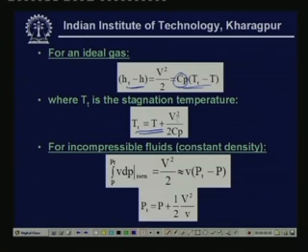Okay. And you have to be careful about the units here. When you are using Cp as kilojoule per kg Kelvin, and if you are using V as meter per second, then you have to divide this expression by 1000, okay, because only then the units will tally. So, you can see here that when the velocity is small, the static temperature is almost same as the stagnation temperature.